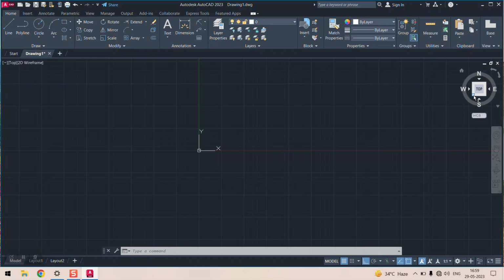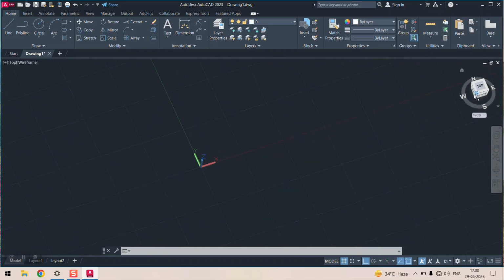So in order to use this, let us suppose I am clicking on the bottom left of the top area. Then you can see I am in this particular coordinate system. So you can see the left of your 3D model from this, and you can see the front of your 3D model from this side with the help of this icon. Okay. If you want to go to another location, you just click on this. See, now you can see the back of your 3D model from this side, and left is available at this side. Again you can click, again it will rotate.